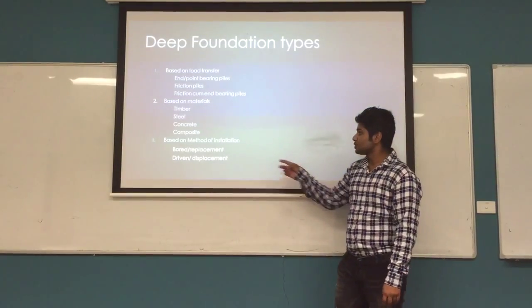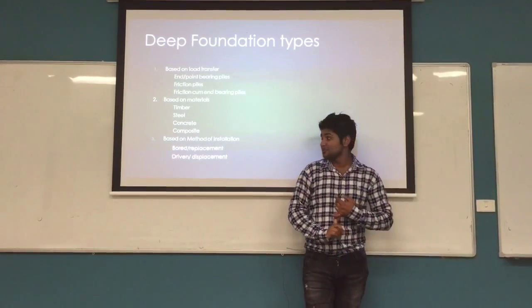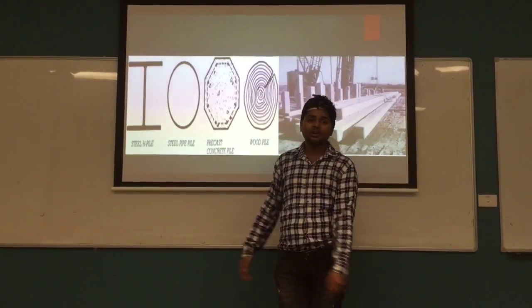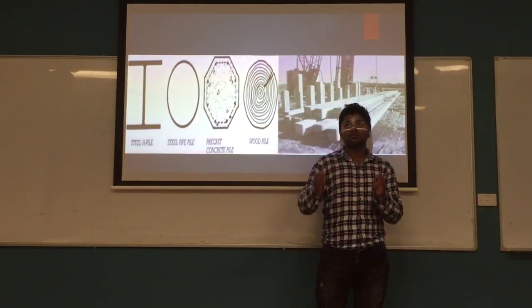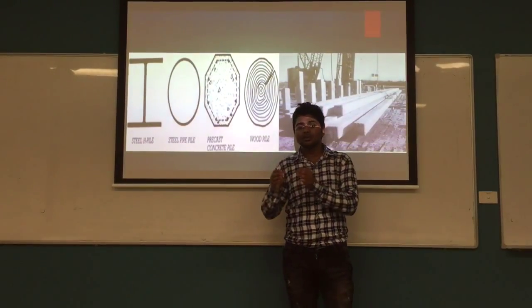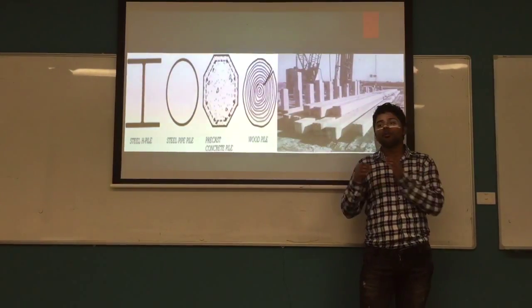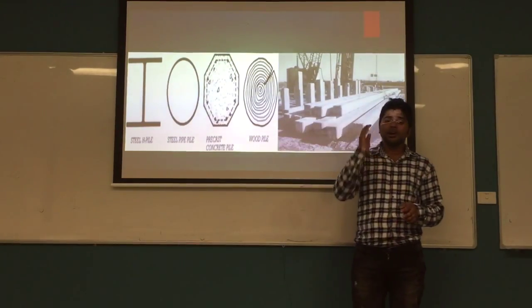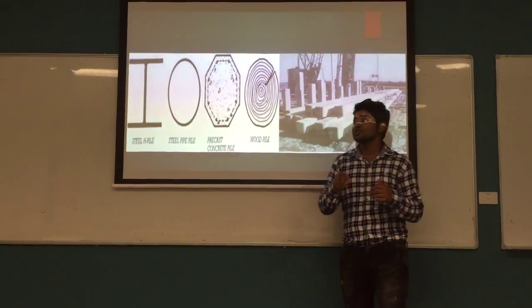There are two different modes of installation: bored, or replacement, and driven, or displacement. We can generalize the concept of the bored pile. In bored installation, we make a pit, bring a pile there, and install it. For the driven ones, we drive the piles directly into the ground wherever it is needed.